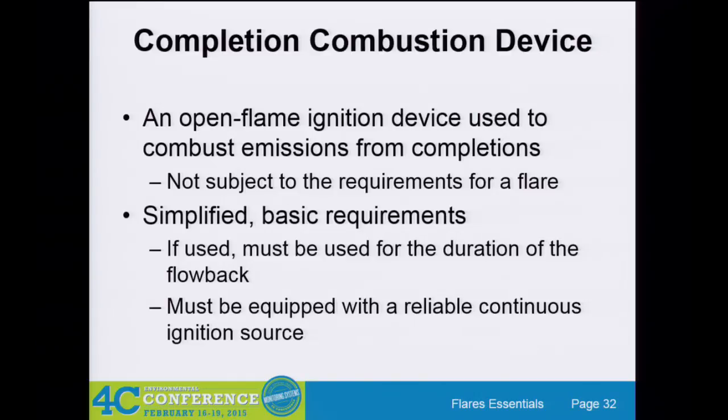Since 60.18 is directed to flares, they basically said, look, as long as you are burning the gas and you're going to get 95% emission reduction, we're going to say we're good. And so 60.18 for completion combustion devices isn't required.